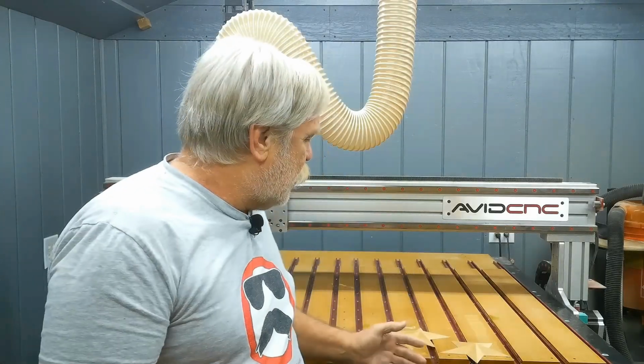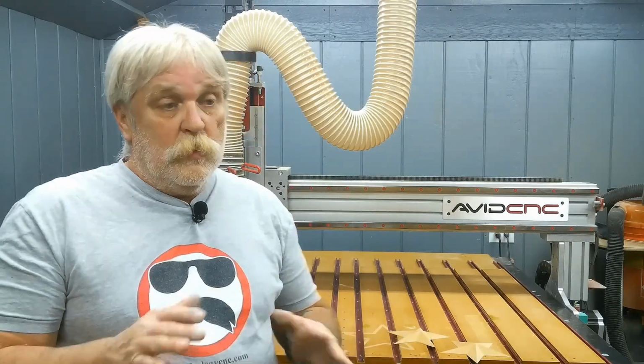But setting that aside, we also learned when it's appropriate to set your Z0 position to the machine bed and when it's more appropriate to set it to the material surface. Now, it would be very easy to say, well, always set your Z0 to the machine bed when you're doing this toolpath or that toolpath, and always set it to the material surface when you're doing this toolpath and this toolpath. But I think there's a little bit more nuance to that. It's going to depend on the project that you're creating and what the priority is.